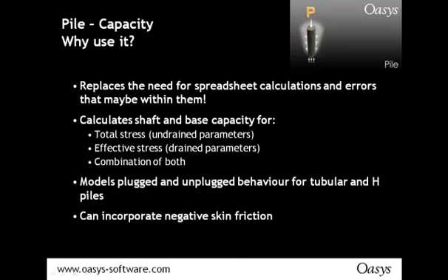It can model more complex tubular or hollow piles because it models the plugged and unplugged behavior where the soil sticks to the inside of the piles. And it can also incorporate negative skin friction.